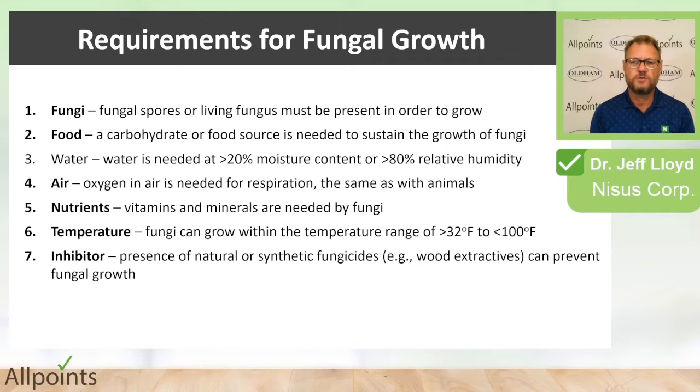Well, the requirements of fungal growth are really similar to the requirements of human beings. So we like to live in a nice home with comfortable temperatures, etc. And so fungi do too. You've got to have the presence of the organism there in the first place, but really consider fungal spores to be ubiquitous in the environment. They're everywhere. Okay, so they're there already, just waiting for the right conditions to grow. Food, you've got to have a carbohydrate source. But most materials in a home can provide that carbohydrate source, whether it be wood or cellulose on sheetrock, or even some building materials supply other nutrients for fungi, such as calcium in concrete and insulation materials.